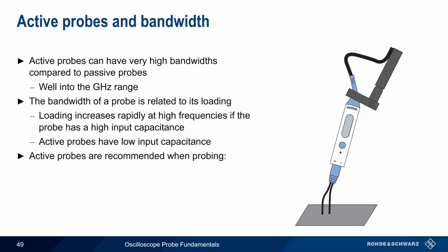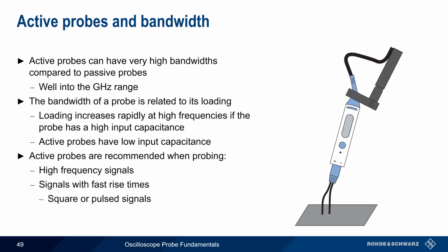Therefore, active probes are recommended for signals that are high frequency and for signals that have fast rise times or significant harmonic content, such as square or pulse signals.